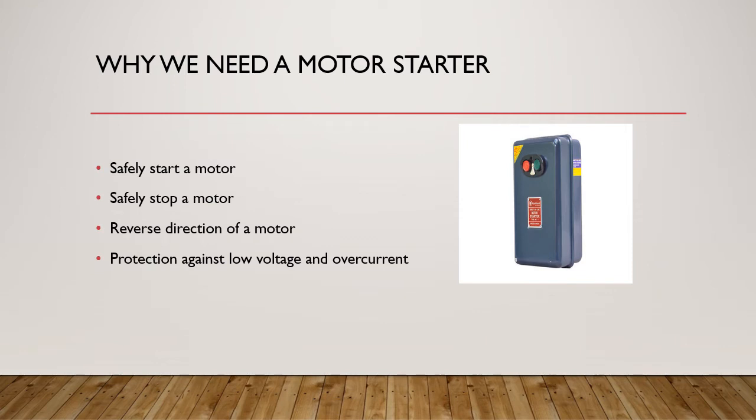Next, it will help us to reverse the motor direction, especially for the forward reverse type of starters. And lastly, a motor starter will protect the motor against low voltage and overcurrent conditions that are caused due to the motor drawing a lot of current when it is starting.